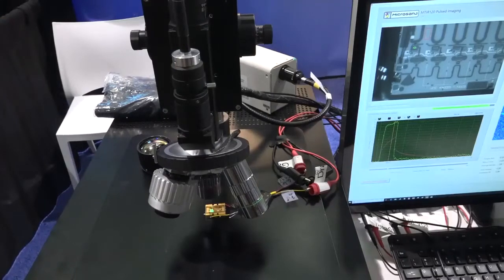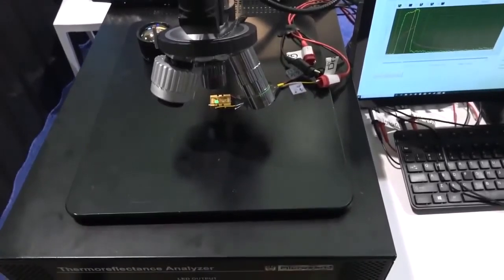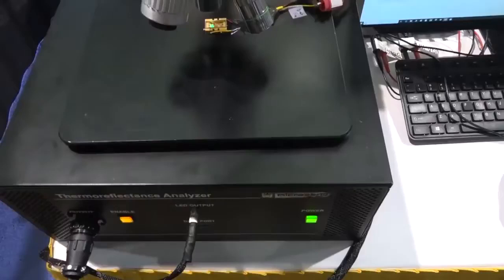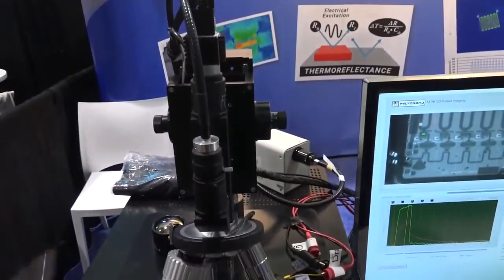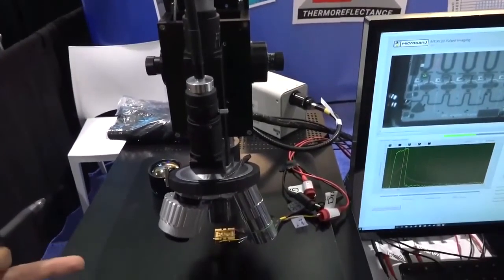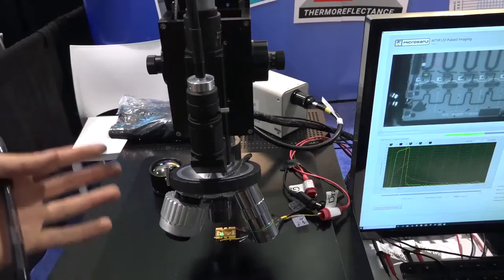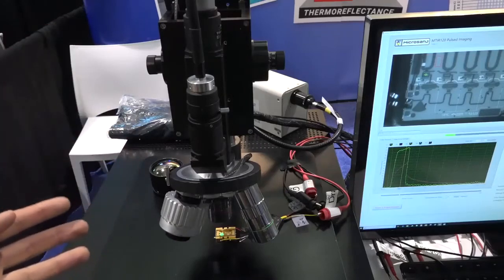So what they do on top of that is that they correlate the shining of this light with a lock-in amplifier that they have designed connected to a camera up here, and everything here is synchronized together. And this allows you to do frames as small as a nanosecond. So you can capture rates so high that you can see the flow of heat due to the flow of electrons in a MMIC with the resolution you would expect to see from an optical instrument, which is absolutely crazy.